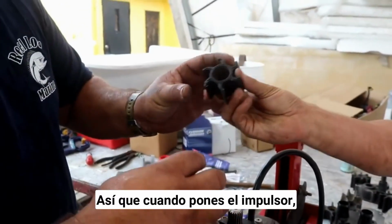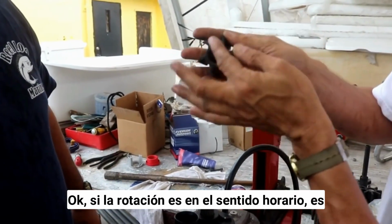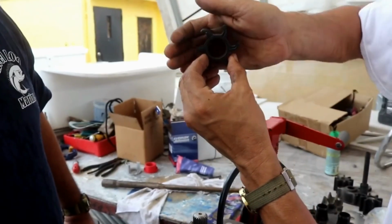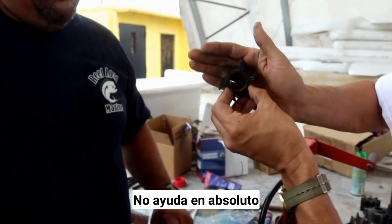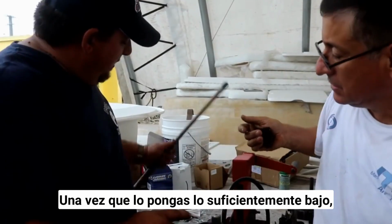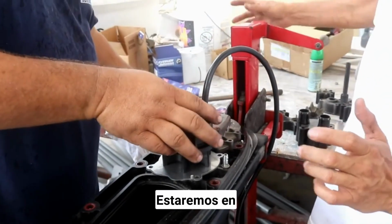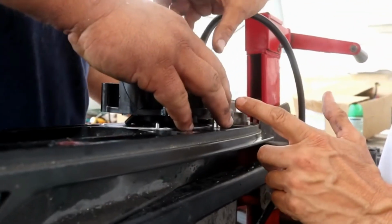When you put the impeller in, you have to spin the housing. If the rotation is clockwise, you should turn the housing in the opposite direction a little in order to help that introduction. Correct. And once you get it low enough, you can put this on there and then twist it by hand. We are going to do the process slowly in order to show the process.